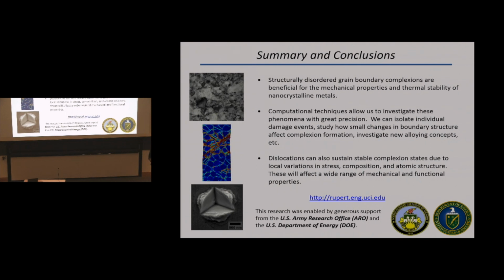Yeah. So I'm just going to reiterate your question just in case people didn't hear it. The question was, if we made the boundaries thicker and thicker and thicker, would we go back to the properties of a metallic glass? Absolutely. So you can think of it almost as a composites problem. We have an issue with nucleating damage at a grain boundary in nanocrystalline. If we have these thin amorphous phases, it can help us absorb that without defects. If those phases became the majority phase, we would start to get shear bands inside that amorphous phase, and we could have localization there.